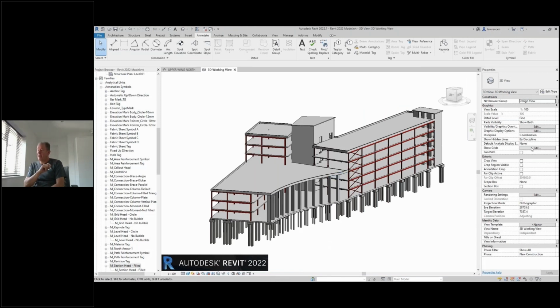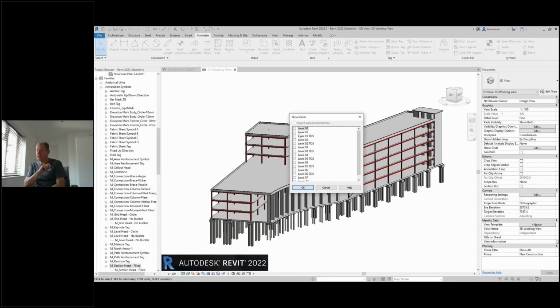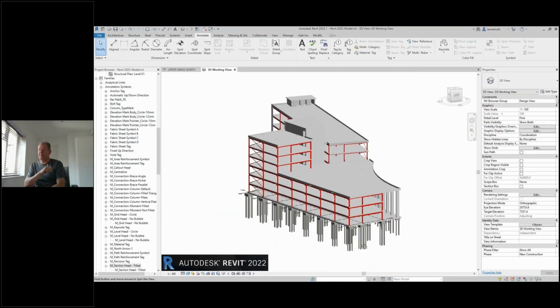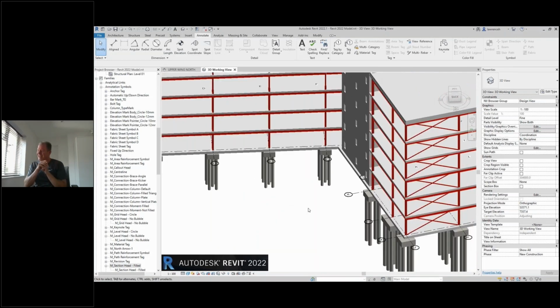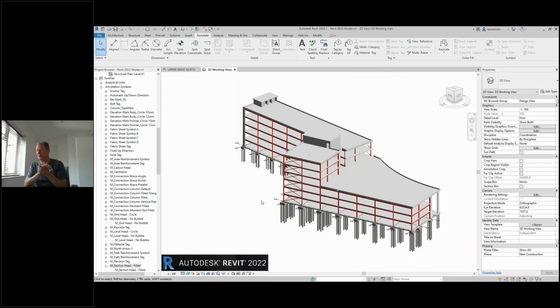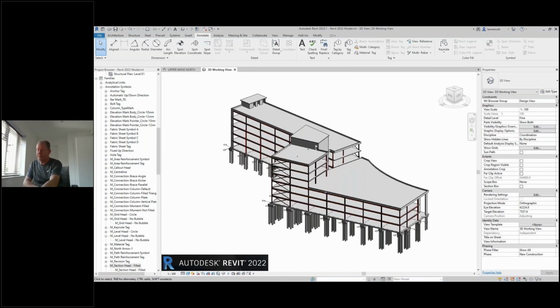Okay, we're also now going to activate our 3D grids. And notice you can do it by level. So I've chosen now to show my 3D grids on level 0, which is our ground floor. And of course, now we can see those 3D grids directly in the 3D view, which is obviously something we've kind of been waiting for a fair old time.